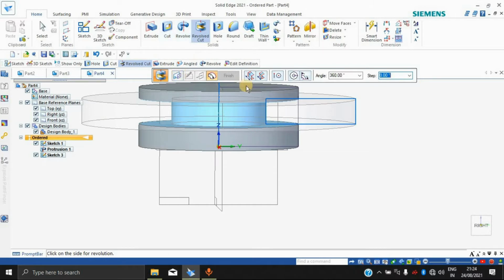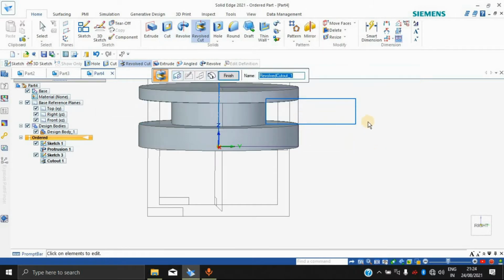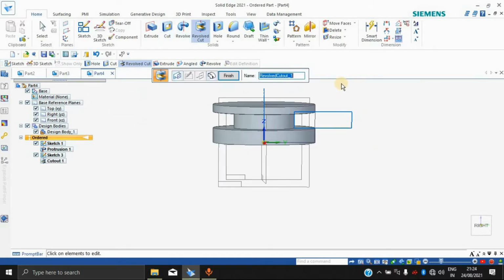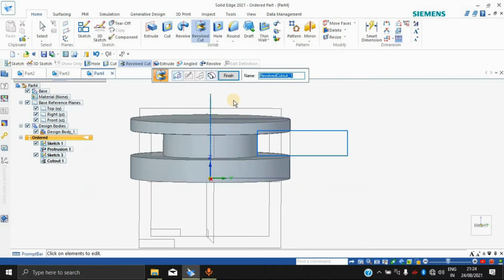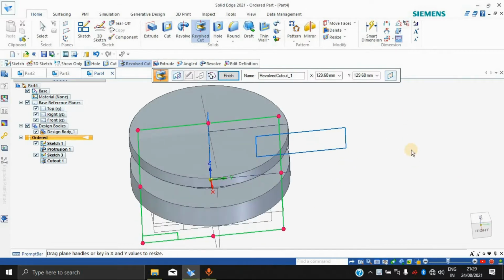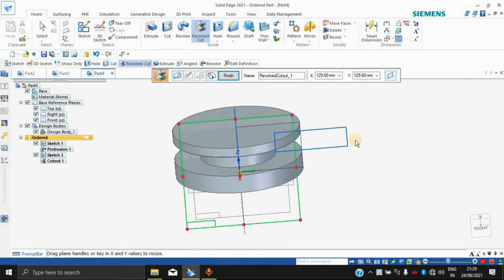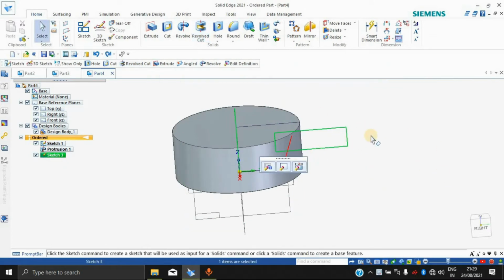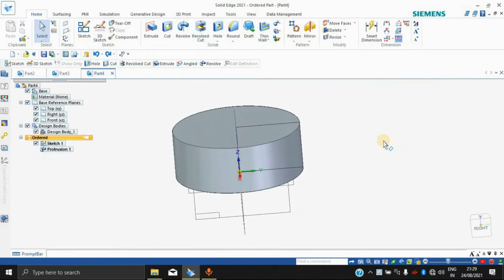See, now it is happening. See how I did? So for revolved, you need two parameters, a line and a geometry. Okay. Now we have seen the revolve command. Just press Control C, Control Z, Control Z.